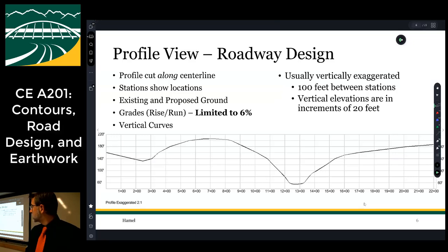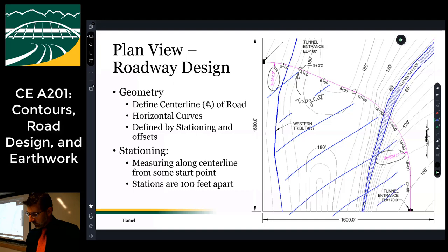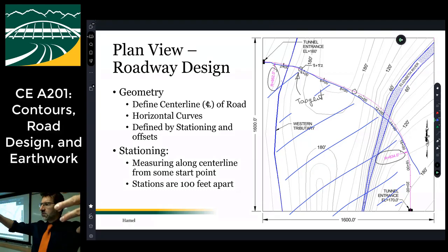So the next thing is basically the combination of a section cut and a roadway alignment. We call this a profile, right? If I could use Fusion, you could see, basically it is if I were to cut this surface or this volume, if you will, along this magenta line and take away all this so that all you can see is the cut along this line, and then you stretch it out or straighten it out, right?